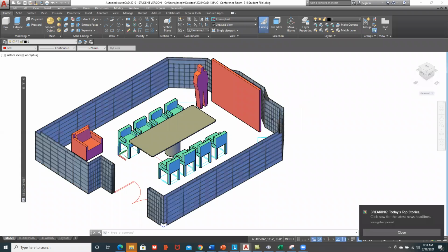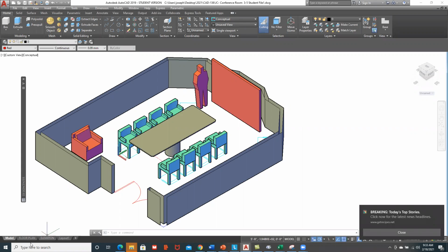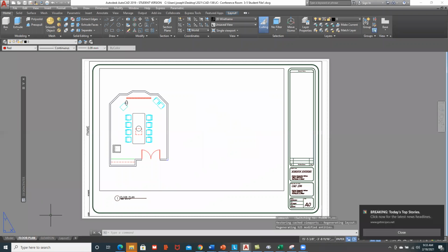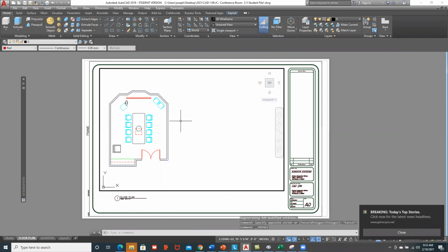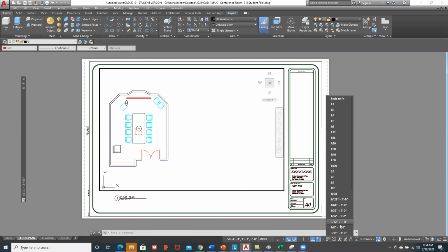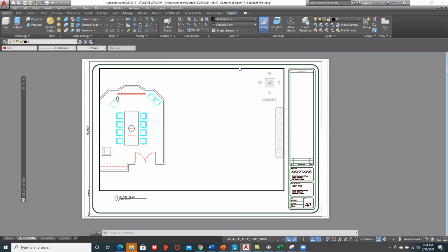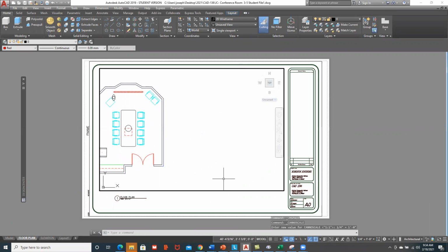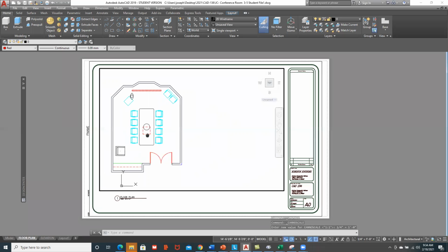Great. And then as we start to work with this, on the floor plan tab, what we want to do is add a viewport. And so the way that we typically display these is with a 2-dimensional view. And what I'll do here is dial in a scale. So we can dial in, let's try, 1/4 inch equals a foot. Here's Martha. Yep. We'll bring this over. And then we'll add another viewport.